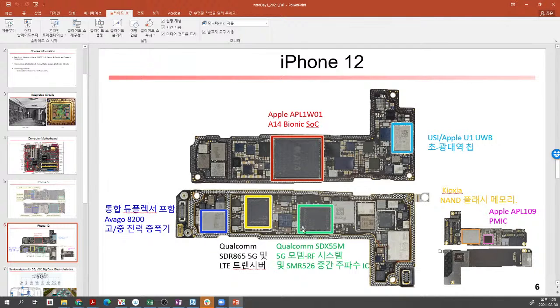On the right-hand side we have a digital chipset that processes all the communication signals. This is the 5G modem. We also have a duplexer on the left, an RF high-frequency component where transmit band and receive band filtering is done.